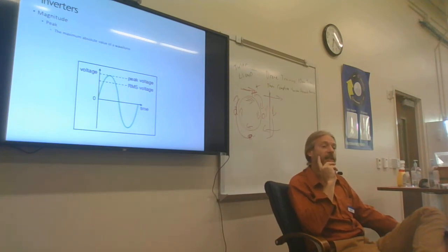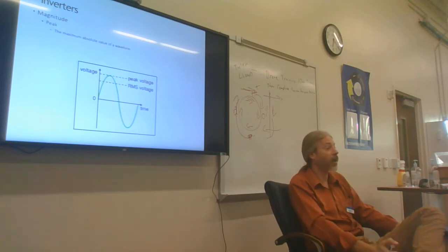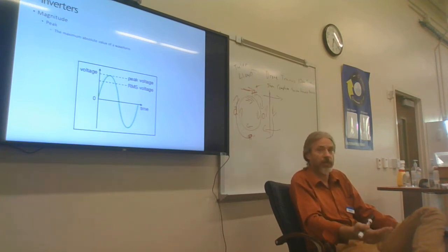I think you guys might be surprised at how much variation a lot of inverters have. Some inverters are capable of outputting as little as 220 volts and as much as 480 volts. They can put out 208 in between. They can match 220, 240, 230, and all the way up to 480. But every inverter has a maximum voltage. Cannot go any higher than that. And obviously you can't hook it up to either loads or the grid at a different voltage.